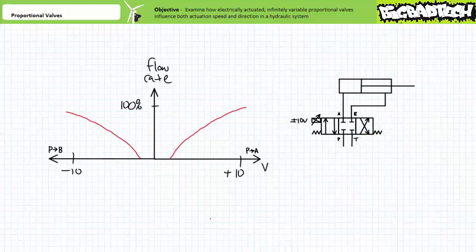By the way, a real flow rate as a function of applied voltage curve might not look as neat and linear as these previous simplifications may have suggested. A real one might observe a little wiggle waggle. However, if you squint your eyes just right, you can see the linear approximation. Additionally, these curves are constructed assuming a constant pressure drop across the valve.